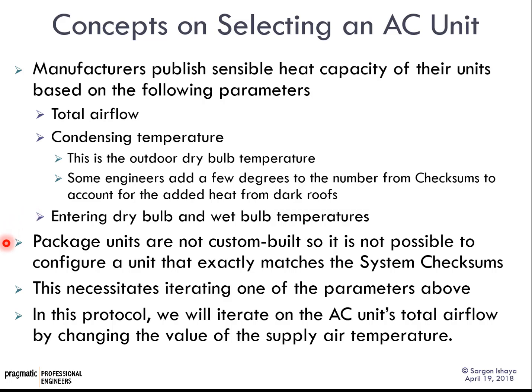A very important note here. The whole purpose of this lecture is basically summed up in this note. Okay? Package units are not custom built. These are commercially available products that are the same when they come off the assembly line. If you buy a 50-ton unit, it doesn't matter where you buy it from. If you buy a 50-ton, let's say, Trane or Carrier or York unit, it's the same thing.